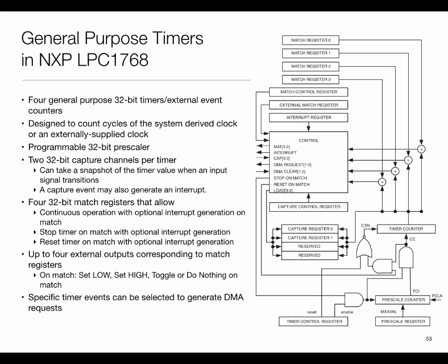And other places where you will see these things is like LED lights. Their intensity is usually pulse width modulated control. So motors, lights, these kind of usually high power things which consume a lot of power. You would often see that PWM signals are used out there both to control the thing as well as for them to convey information. And like I said, the main thing you win is a single wire on a ground. So just a pair of wires can convey information. So accordingly, processors provide support for it, and these kind of features help you do that.